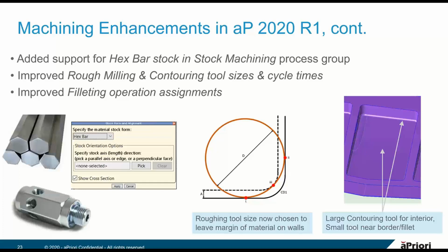And especially when you get down to smaller tool diameters, a somewhat larger diameter has a pretty big impact on reducing cycle time. And we did something similar in the case of contour finish milling, as shown in this picture of a purple part. This is sort of a pocket, but the bottom of that pocket is not a plane. It's kind of a curved, lofted surface. You see these on aerospace parts quite commonly.